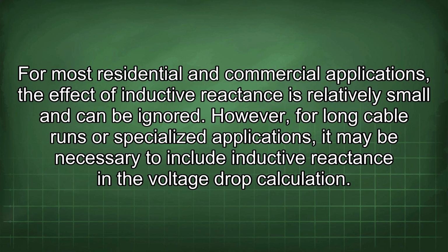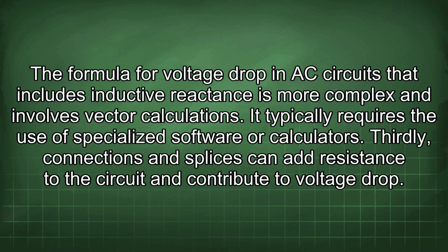However, for long cable runs or specialized applications, it may be necessary to include inductive reactance in the voltage drop calculation. The formula for voltage drop in AC circuits that includes inductive reactance is more complex and involves vector calculations. It typically requires the use of specialized software or calculators.